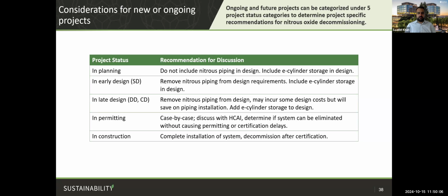decommissioning. So for projects that are in planning, in early design, or in late design, we are not including nitrous oxide piping in the design, and instead providing e-cylinder storage in the design.